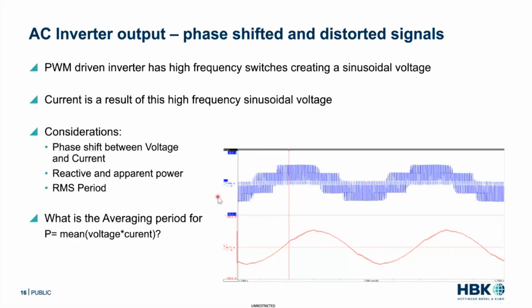So we just went over in the DC, you know, this motor is an inductor. This motor that this AC voltage is going into introduces a phase shift. So our voltage and our current are just, by definition of going into a motor, going to be phase shifted. So when we're measuring power, we need to consider what that phase shift is.